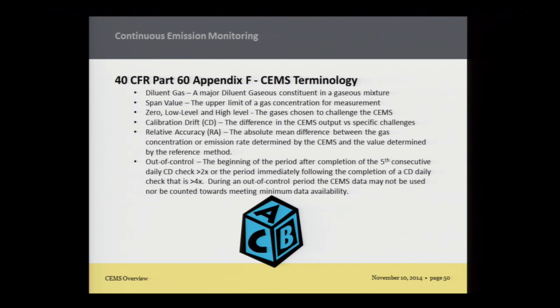So it's a good point and something to look for, because if you had a picky enough auditor come in, they could look at that and say, "Can you go show me the logbook when you were 2 times out on day 1, and let's see what you did to try to correct it." And if you didn't do anything, potentially you have a deviation there. I've never been asked it. I'm not sure that most of the regulators in Texas know that to that detail. But I don't have a lot of experience outside of Texas and Utah with CEMS from my experience at URS.